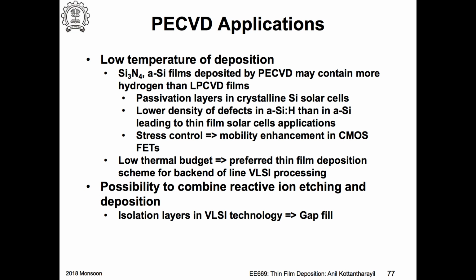Okay. A display has to be refreshed at what rate? Maybe 30 frames per second. So it doesn't have to be very fast. So you use inferior quality semiconductors which don't have very high mobility. One of the candidates is amorphous silicon. Okay, so somebody was asking this question. Amorphous silicon is very defective. Okay? Bonds are broken, there is no crystalline structure and so on.